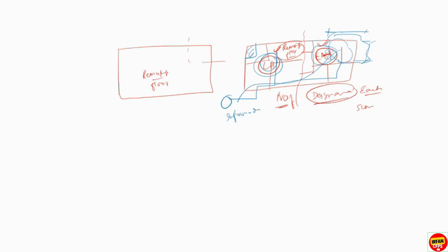And for light hazard, you will select the remotest area and perform the calculation. So in this case, you will consider two scenarios. But in your project, if you have a 10 floor building, for example, I am explaining various scenarios so that it will be easy for you when you perform the calculations.